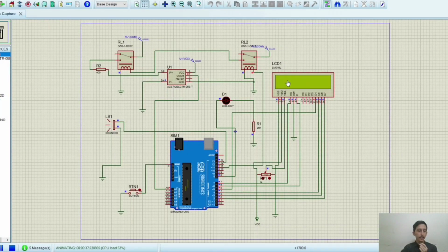From my research, a 12 volt relay in good condition draws around 30 milliampere up to 100 milliampere. So for this condition, the relay is in good condition.